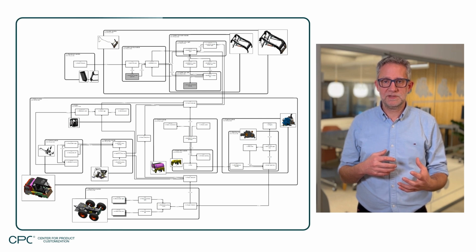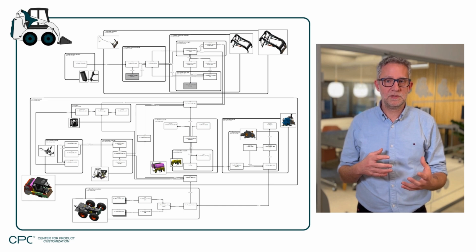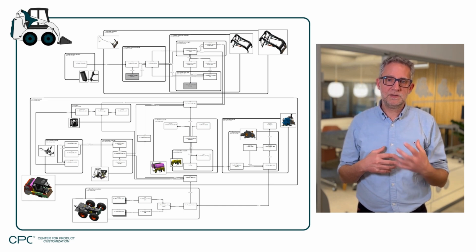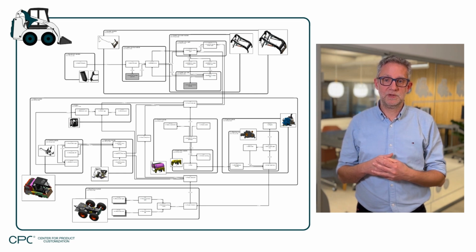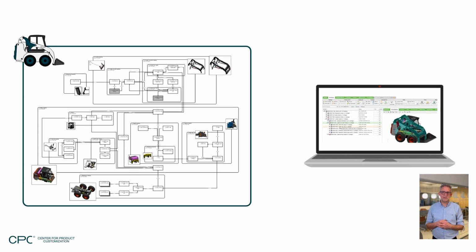With a completed interface diagram, we have a schematic that represents an overloaded product structure for a family of products, which is the foundation for a modular product architecture. To define individual product variants, we can use another CPC tool. Having a schematic overview of the product structure can be good for facilitating cross-functional discussions, but to fully reap the benefits of modularization, it is important to ensure that the product structure is utilized by the organization.